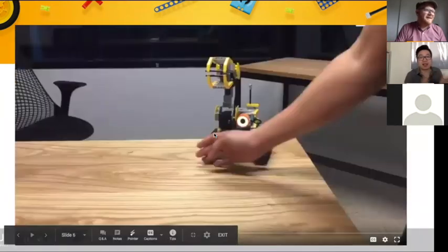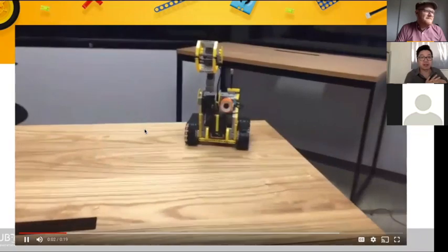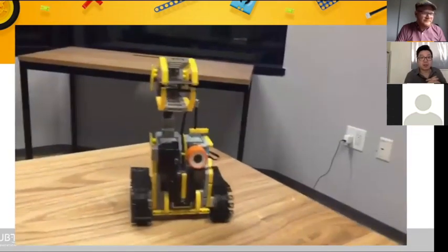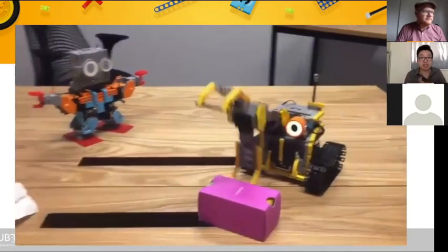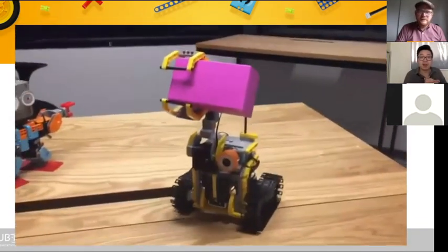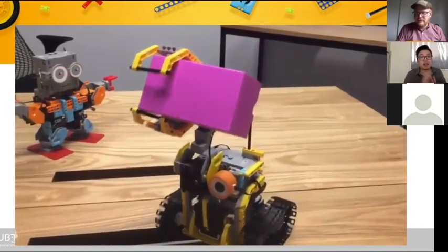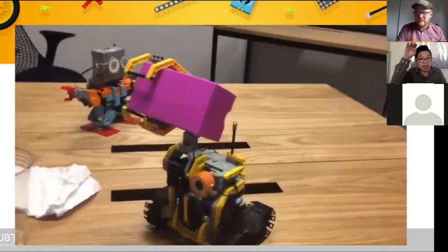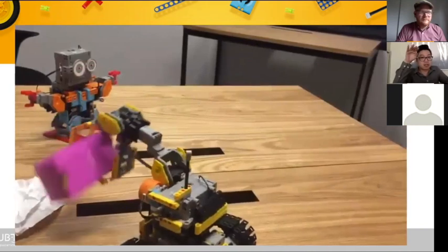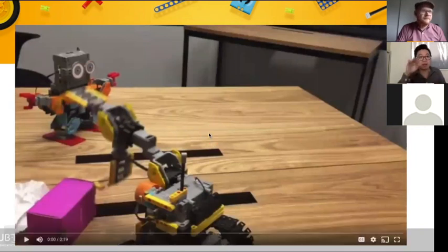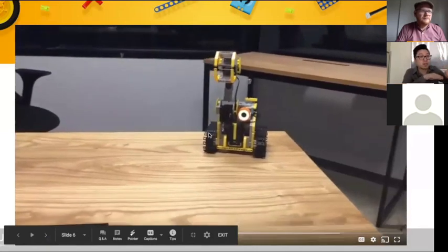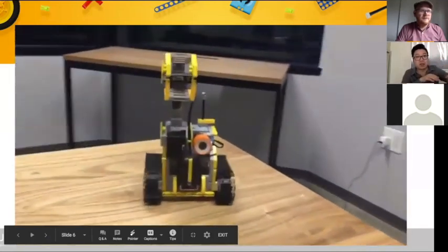So first, I was like, it definitely needs some kind of rangefinder. So an IR sensor naturally is a good choice for these types of tasks. So I was like, okay, let's put an IR sensor on it. But then if you put the sensor too high, you won't be able to detect small objects. So we decided to put the sensor at the bottom, so the robot will be able to see most of the things. But one tricky thing about an infrared sensor: you can't put it too low. It will constantly see the ground, and then the sensor will lose function as well.